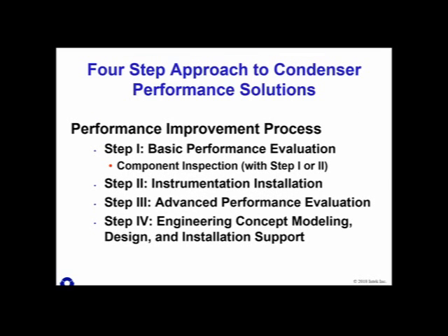So one of the last things that I'm going to talk about today is condenser improvement projects, condenser upgrading projects. I've talked a lot about the Westinghouse condenser being a poor design. There are some Ingersoll Rand condensers that are very poor designs. I've shown you the thermal performance profiles and where there can be dead zones that are always there. No matter what you do, you can reduce air in-leakage to very low levels, and those areas will still be bound up. I've shown how fouling can affect performance.